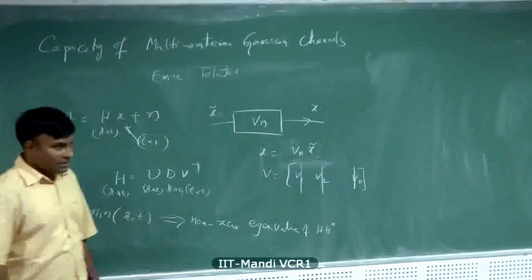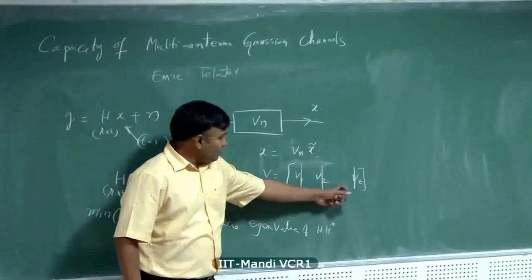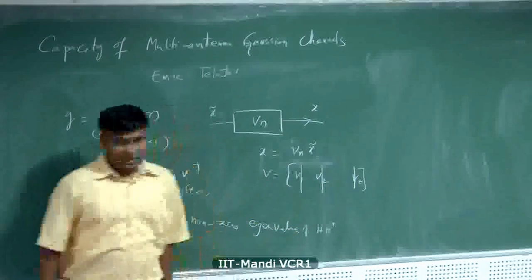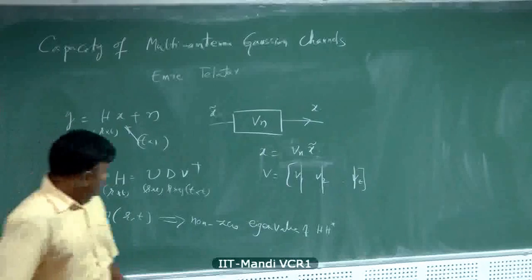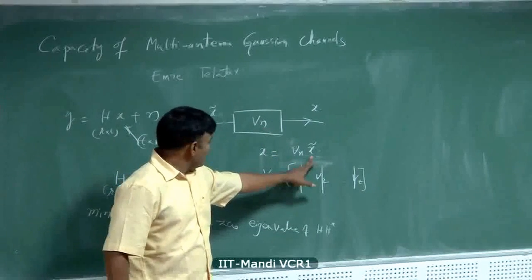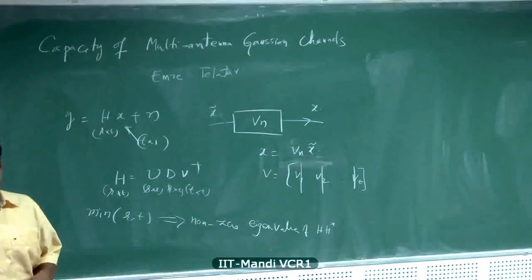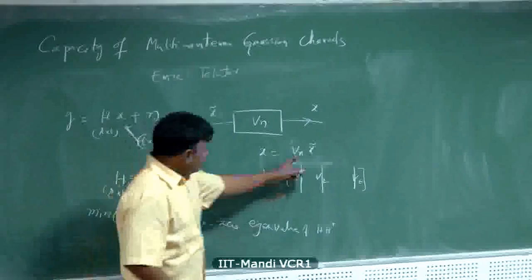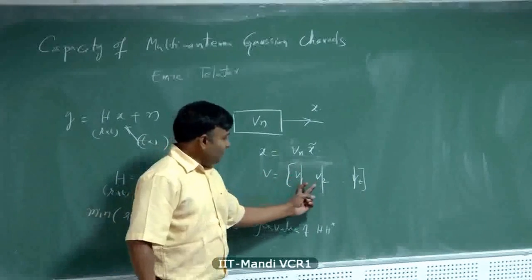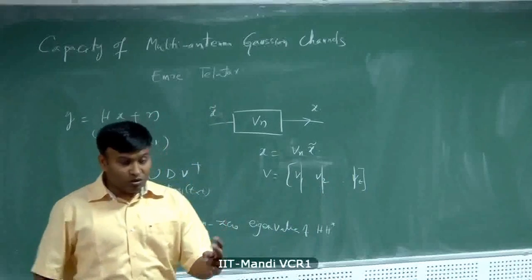So you can choose any number of columns from this V matrix as the beamforming matrix. If you choose 1, then the dimension of X tilde becomes 1. It becomes a scalar. Then we call it single stream beamforming. If you choose n equal to 2, you send 2 streams with a beamforming matrix of V1, V2. You can perfectly recover them.